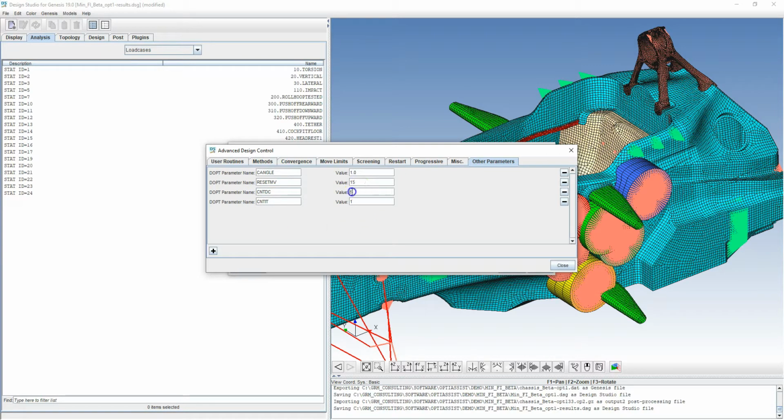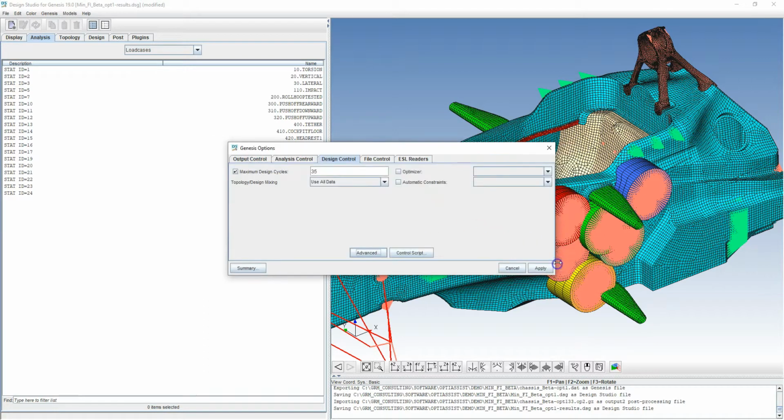And what this will do is it will mean every 5th iteration, a full contact iteration will be performed, and in all the other stages, so every sort of 2nd, 3rd, 4th, it will only perform 1 iteration and just continue from the previous converged state. So that solves a lot faster for your contact problems.